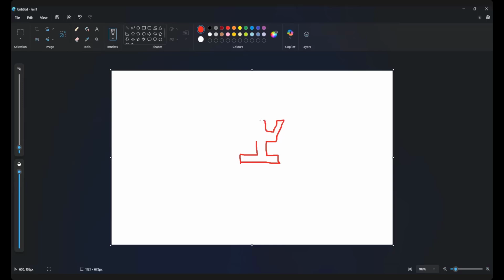You have to draw like this. First, you go part by part. First, the inverted T shape. After you have done the inverted T shape, then you will draw the crown. So for the crown too, you need to set relations, equal, perpendicular, and so on. Okay, we will do this. I will show you how we do this. Understand, class? So this is a base profile.